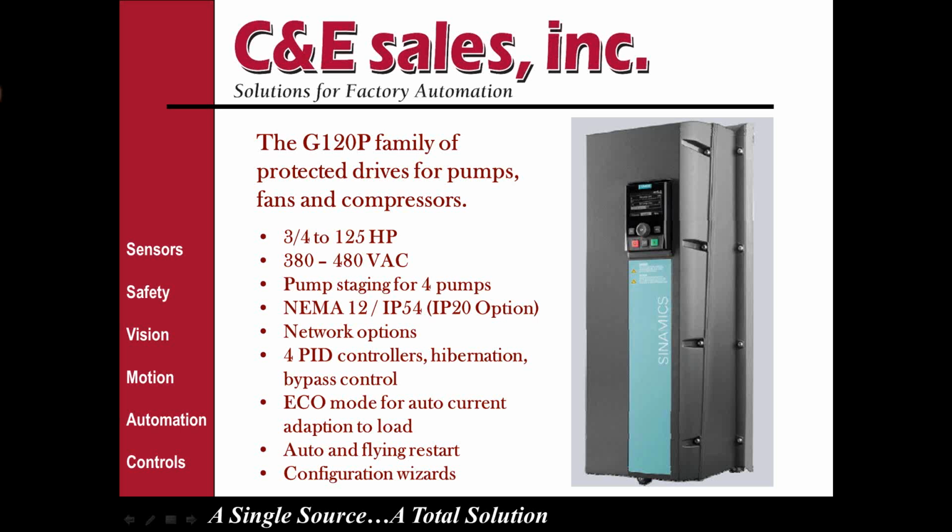Quite often that needs to be done in a PLC or done through other timers or sequencing. That capability is now built into the G120P family. So again, you can save costs in your application by doing everything in the drive. Formerly, that might have required external equipment to do your control.